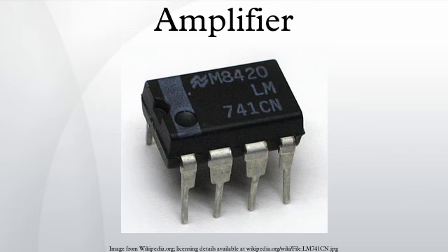Also, Class E and Class F amplifiers are commonly described in literature for radio frequency applications where efficiency of the traditional classes is important, yet several aspects deviate substantially from their ideal values. These classes use harmonic tuning of their output networks to achieve higher efficiency and can be considered a subset of Class C due to their conduction angle characteristics.